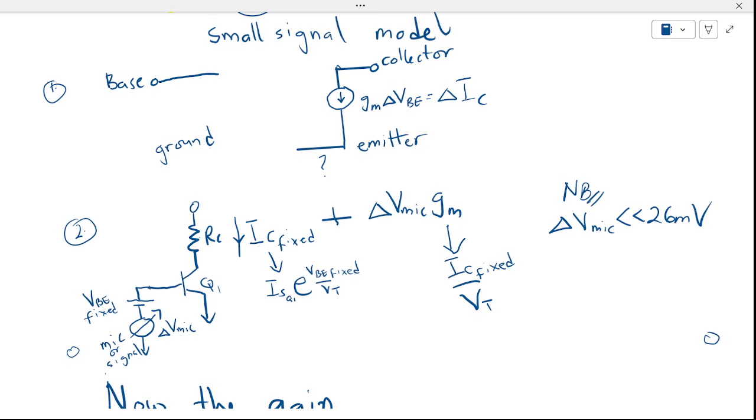So if I'm looking at this, I have the transistor biased to get a particular transconductance or a particular IC, which is fixed before the transistor can operate properly. Depending on how much gain I want, I need to set the bias voltage to fix that. Then the signal comes in from a microphone, giving changes in, let's say, plus or minus 10 millivolts. Easier to use these values as an example. Okay, so we can model that in what we call the small signal model.